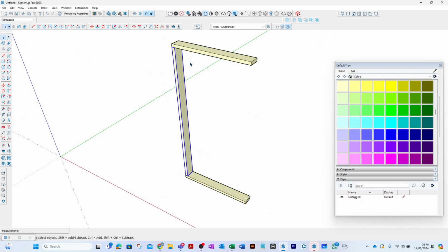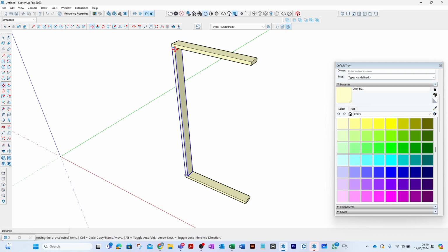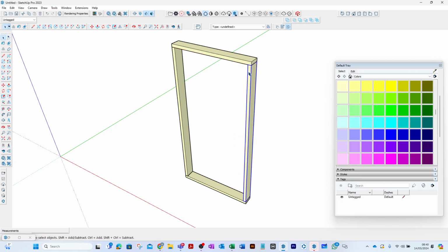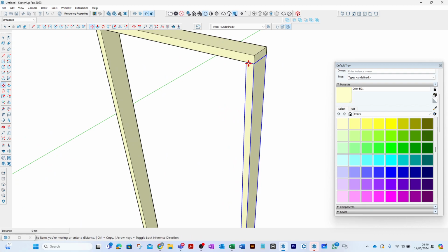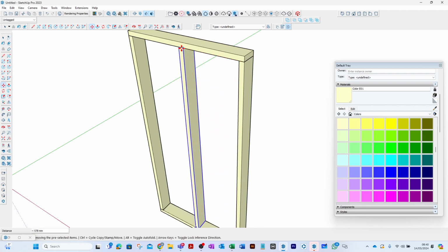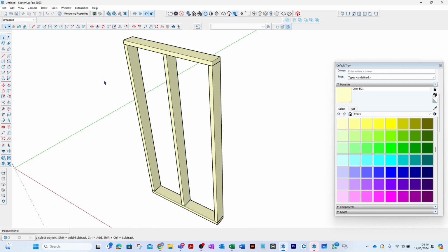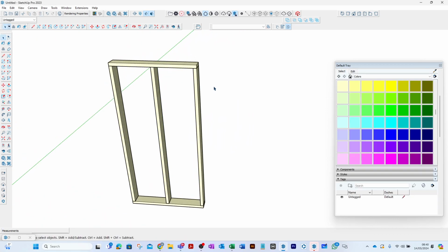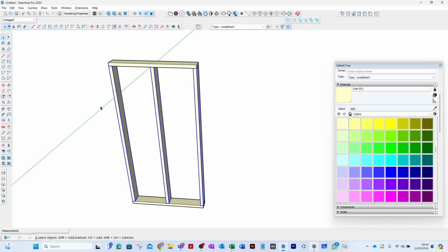And I'm trying to draw an off-site manufacturer panel, and then what we'll do is we'll copy that along to the very end, and then as expected I want another one of these but flat bang in the middle. Right, if I select all of these, these are the 3 studs. I now need to give them an IFC classification.